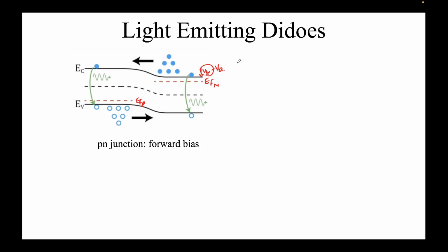That's why I was telling that for light emitting diodes, we operate in the first quadrant. Solar cells, we saw we were in the fourth quadrant, the photovoltaic mode, and photodiodes, we saw we were in the third quadrant, the photoconductive mode. Second quadrant, I have not seen much use of it, but there are some exotic devices which work even in the second quadrant.